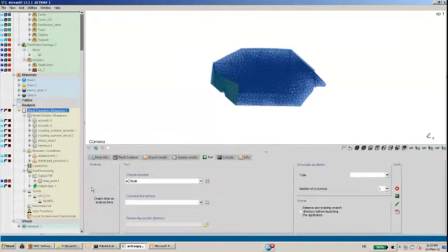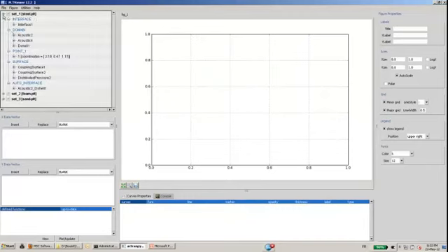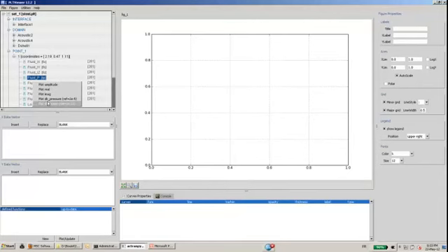Okay, so then the next operation is to run the analysis. I can do that directly from Actran VI, or I can launch it in a prompt. To gain some time, I've already done that. So we will directly look at the results. Here are the three results files: the steel PLT, the foam PLT, and the sandwich PLT. I will plot the sound pressure level at the drivers here. So I go here, and under field pressure, I right-click, plot dB pressure.